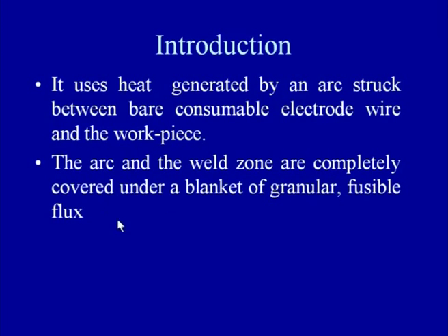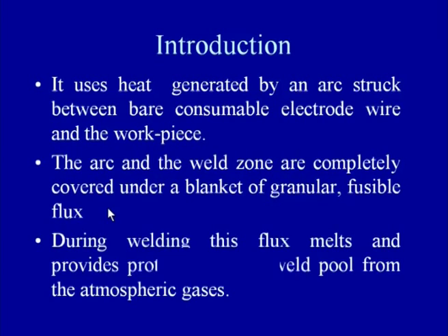So, this blanket formed by the granular flux melts continuously by the heat of the arc during the welding, and thus provides the required protection from atmospheric contamination. During the welding, this flux which is covering the arc completely melts and provides protection to the weld pool from the atmospheric gases.